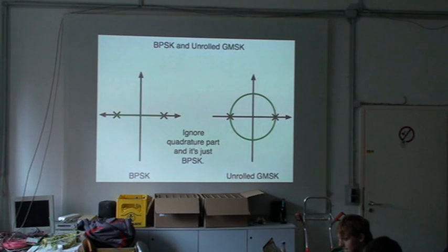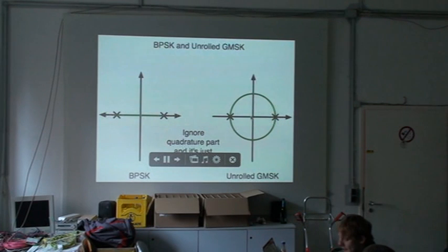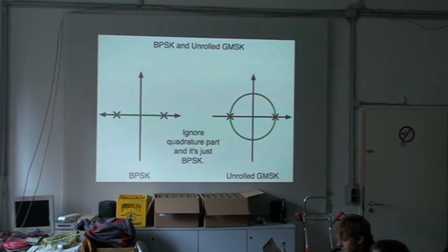this signal and slice it, we don't really slice it. We just quantize it along that axis, and we preserve that information. Because if we slice it, we may take a symbol that was close to the origin, of somewhat indeterminate value, and artificially force it to one side or the other. If we do that, we're destroying information. So we don't destroy the information, we just quantize it.